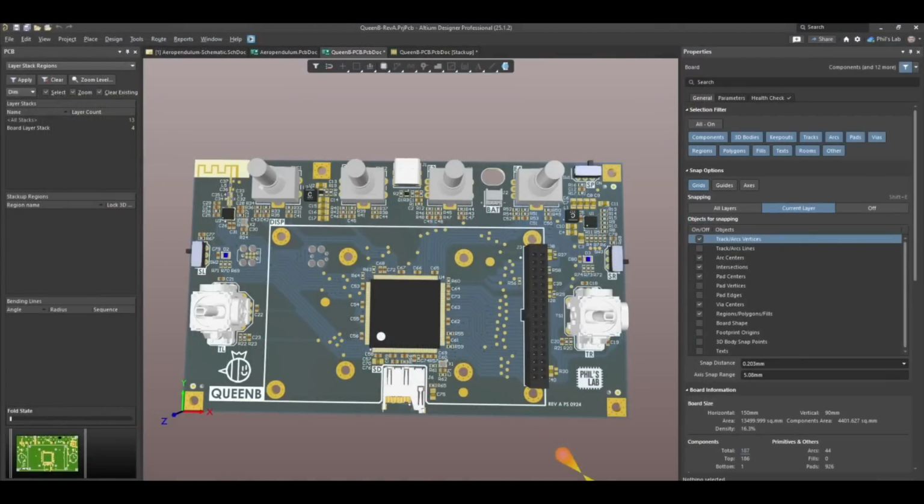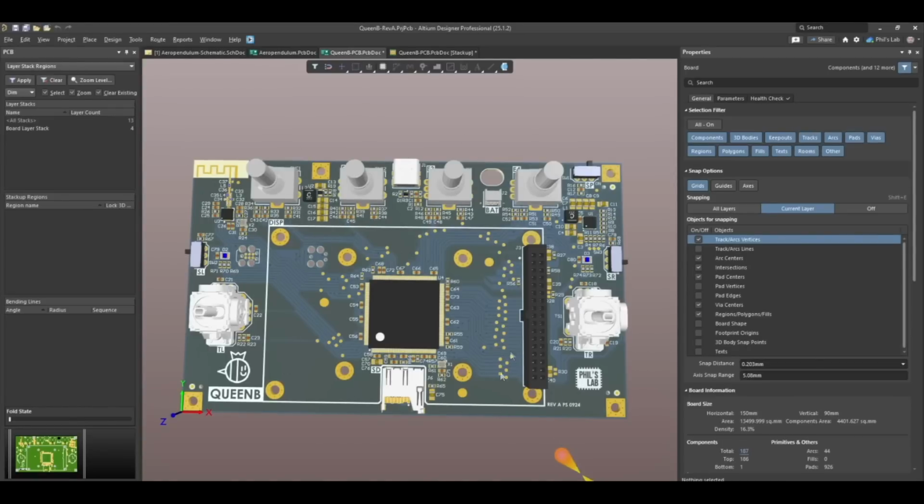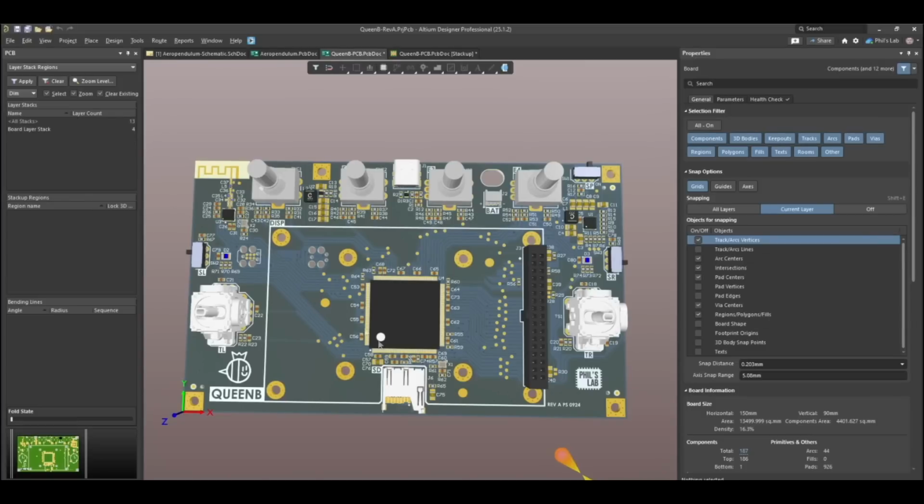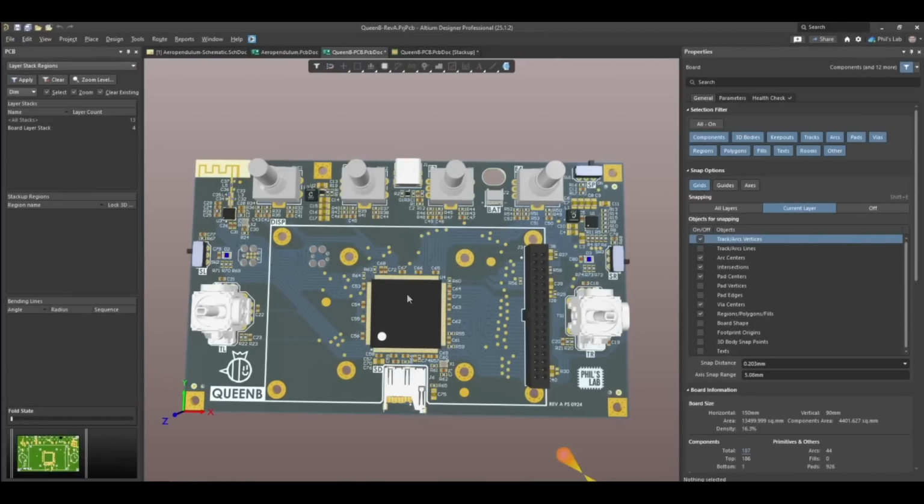Just to show you a more real-world practical demonstration, I'd also like to show you a quick measurement or two on the Queen Bee radio control PCB that's featured a couple times on this channel. For this experiment, I'm simply setting up the STM32H7 microcontroller, one aggressor output, which will just be a 100 kilohertz timer square wave where I can control the output drive strength, which gives me rise and fall times adjustable from about 1 nanosecond to about 6, 7, 8 nanoseconds. So we can see the impact of increasing and decreasing the rise and fall times on the crosstalk. And another output channel I'm just going to be driving as GPIO low, which will then be our victim trace.